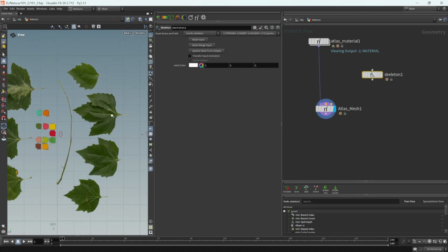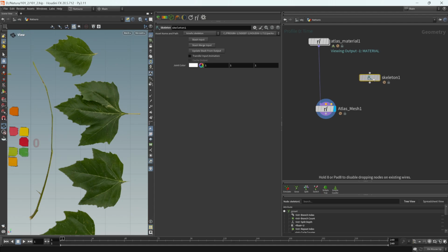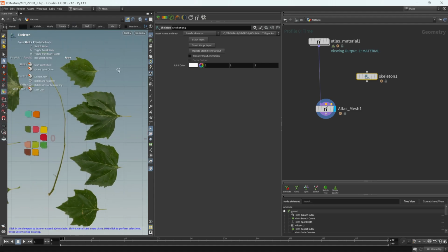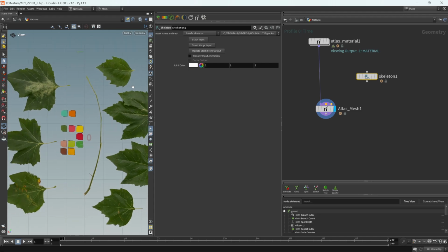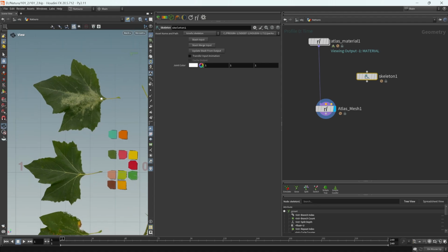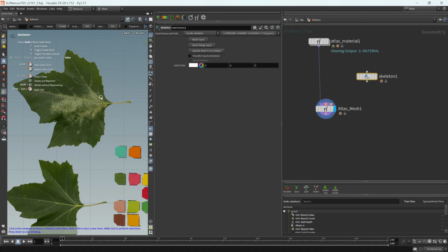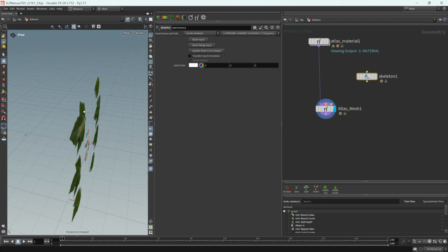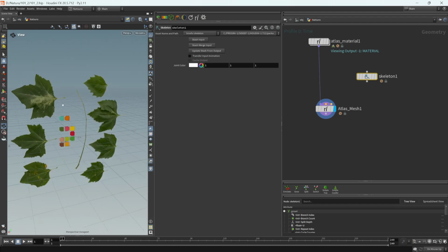While in the back view, I'm going to go and click on the skeleton node once more, click inside of the viewport, and press enter. This means we're now inside of an interactive state in the viewport. The way that Houdini handles interactive states can be a little bit alienating for newcomers, but you'll get the hang of it after a while. I'm going to go through that once more. You can press escape to exit the state, and I'm back in the perspective view.